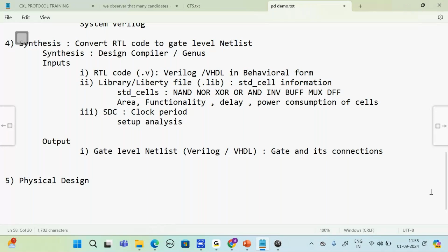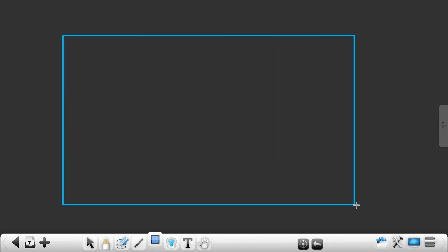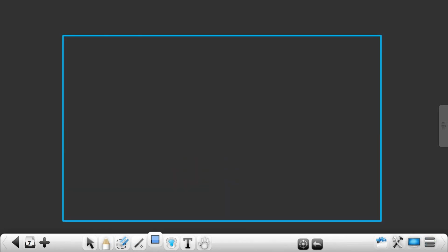So, first, what we start with this physical design is partitioning. So, what we do, right? In the netlist, I have cells. Netlist is giving me all the cells, right? I have totally 4 crore cells. What we do, entire chip, whatever I have, this chip we partition into different blocks like this.